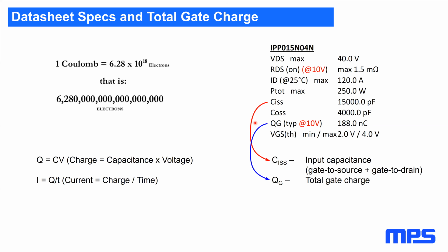Okay. In many schematics, a resistor is present between the gate and source, 20K ohm, for example. What is that for? That's there just to make sure that the gate is always at a known voltage. One thing you don't want to happen is to let the gate float. If the gate floats, you'll get false turn on, and you might get partial turn on from leakages as the gate voltage might creep around.